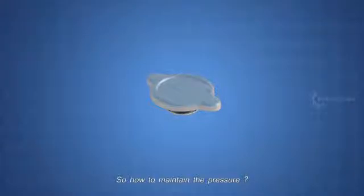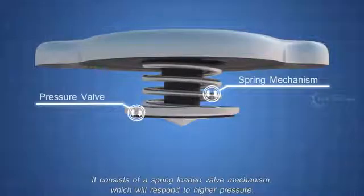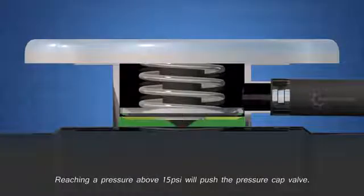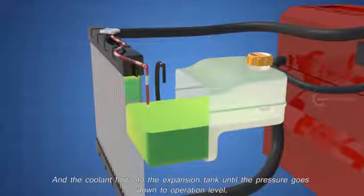So, how to maintain the pressure? Here comes the role of the radiator pressure cap. It consists of a spring-loaded valve mechanism, which will respond to higher pressure. Reaching a pressure above 15 psi will push the pressure cap valve, and the coolant flows to the expansion tank, until the pressure goes down to operation level.